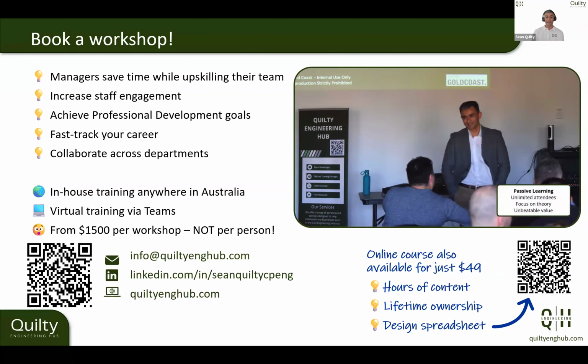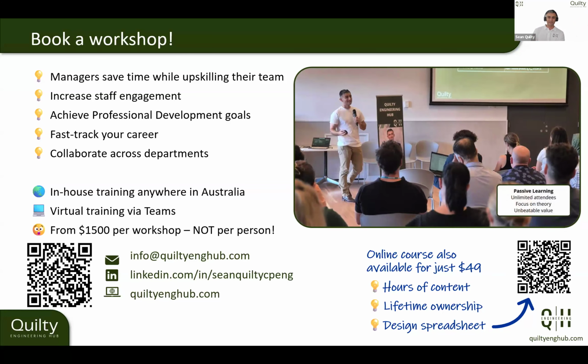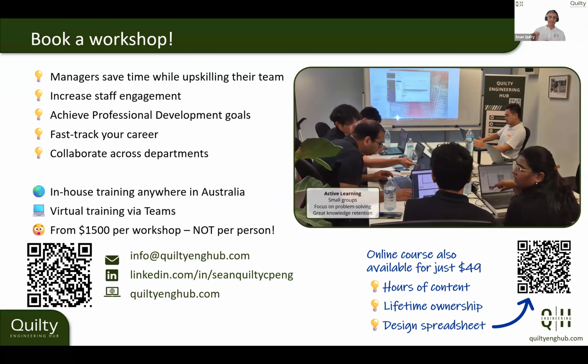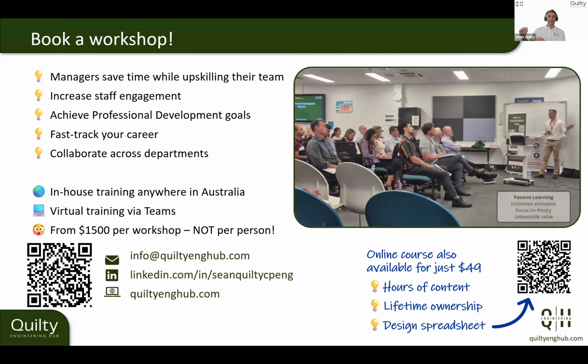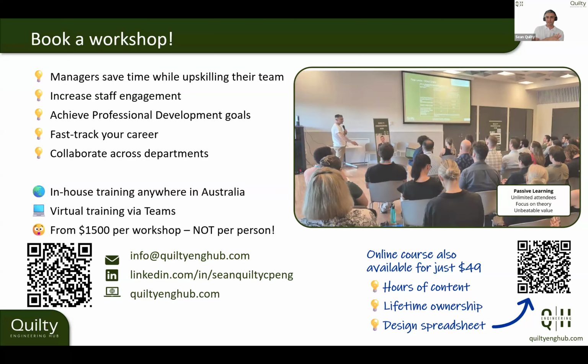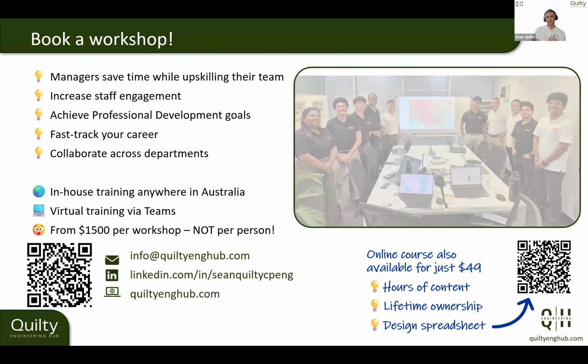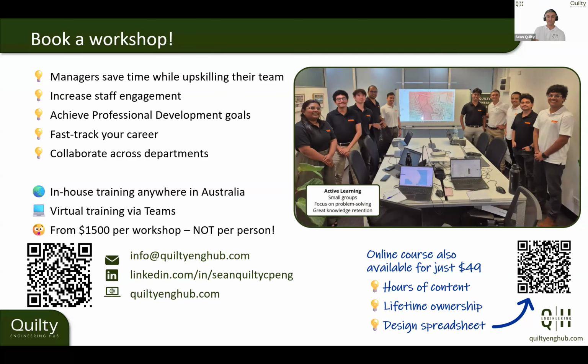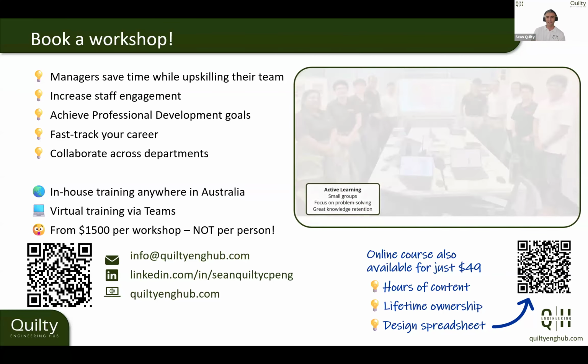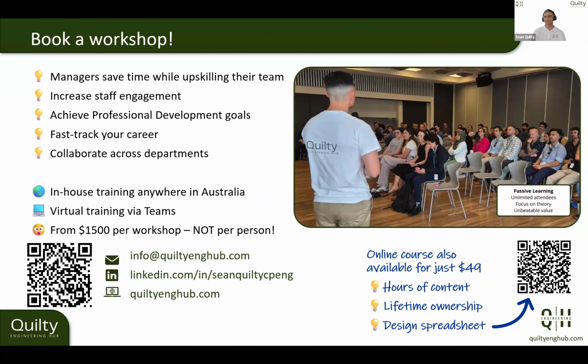In that case, it might be bare earth, so the grass hasn't actually struck yet. And if that's the case, then your Manning's value would be like 0.02 or 0.025 or something, pretty smooth. The problem with that is, if it's a smooth channel and you crunch the numbers with Manning's, you're going to have a very high velocity. So if you've got a high velocity, then you've got to look at what the threshold is between the velocity of the water and the surface. And if it's bare earth, it's very easy to erode. So your acceptable velocity, or your maximum allowable velocity, will be quite low. I'm just picking numbers out of my head, so don't quote me on the numbers, but you might be limited to, say, 1 meter a second. You can't have more than 1 meter a second.